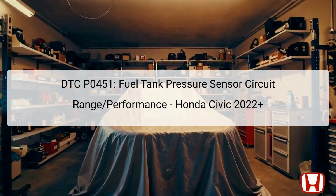The Diagnostic Trouble Code, DTC P0451, pertains to the fuel tank pressure (FTP) sensor circuit, indicating a range or performance issue. When the powertrain control module, PCM, detects irregular electrical signals in the FTP sensor over a specified time frame, it registers this anomaly as DTC P0451.